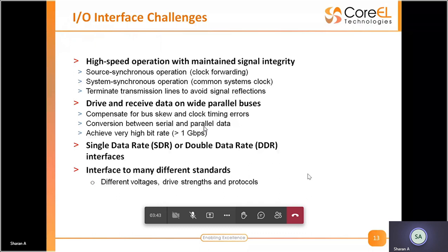Some will be operating at 3.3 volts. Okay, so 1.8 volt pins are mainly for data transfer, and 3.3 volt pins are generally to drive input or output. Generally, if you take your LEDs or your buttons, usually they'll be 3.3 volt. Okay, but for data transfer pins, they'll be under 1.8 volt.